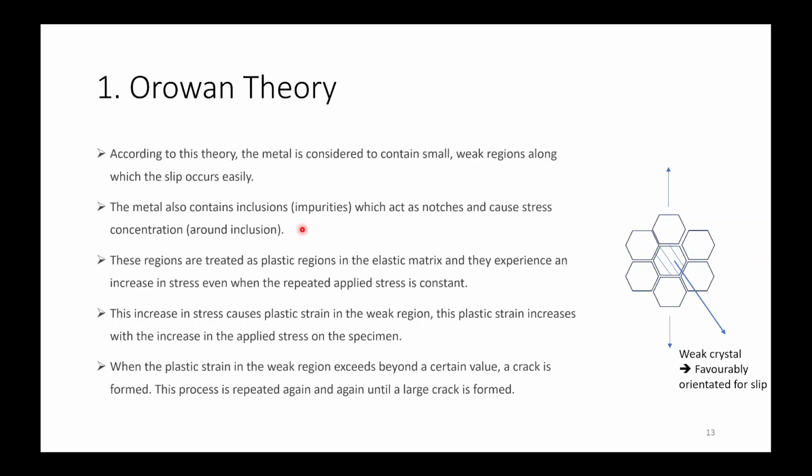As I told earlier, it will act as composite material, so there will be some interface there. Okay, ma'am. If carbon is there, carbon will be in interstitial. It is improving strength. So solid solubility you must have studied, right? Solid solution. So it will be improving strength of entire material. Inclusion will also improve strength, but it is providing some interface as well. That is what will be causing weak regions in material, which can lead to formation of cracks.